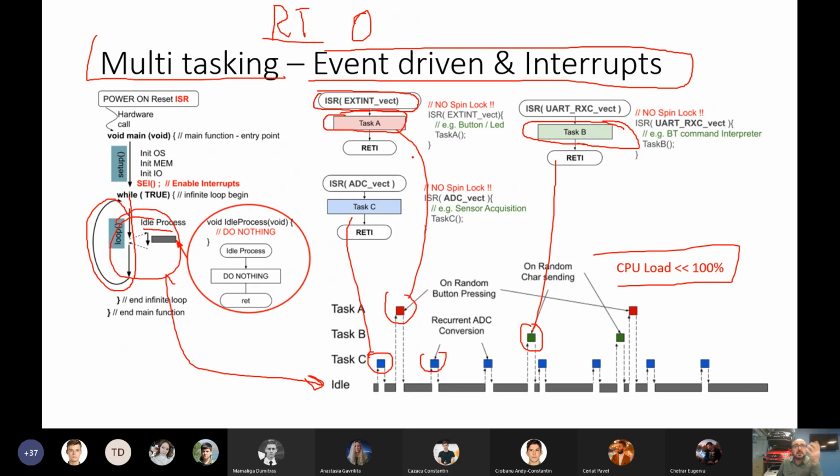One microcontroller can have only a few external interrupts; we don't have as many interruptions or peripheral modules as we have tasks. So it's okay for a small application, for very real-time, but it's not good when we want to scale. And usually when you port from one microcontroller to another, we have to redefine everything according to the hardware of the next microcontroller.